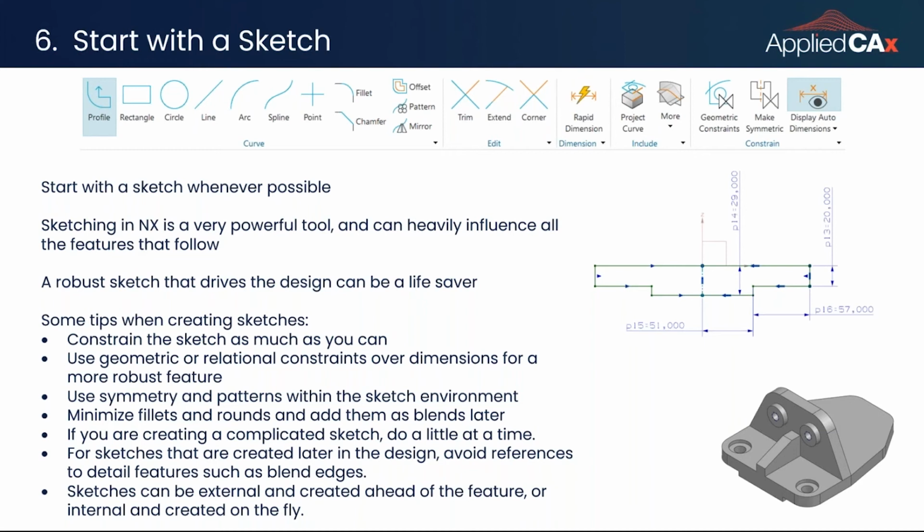Sometimes you do want that relationship so that if something changes, that sketch does change. So in that case, feel free. And then one thing I'll mention with sketches is that you can start with a sketch and then jump into a tool, making that sketch an external feature on the feature tree. You can also jump into a tool, and a lot of them will have the ability to jump into the sketching environment and have that as an embedded feature.